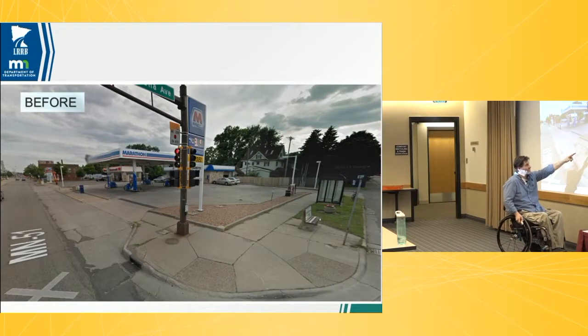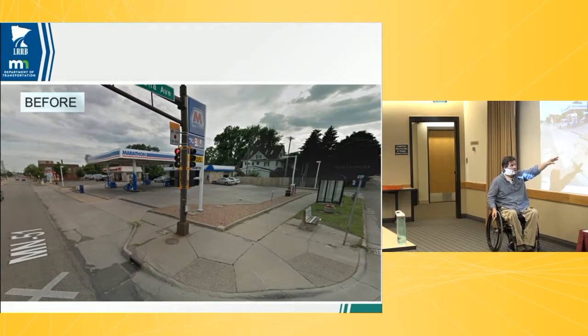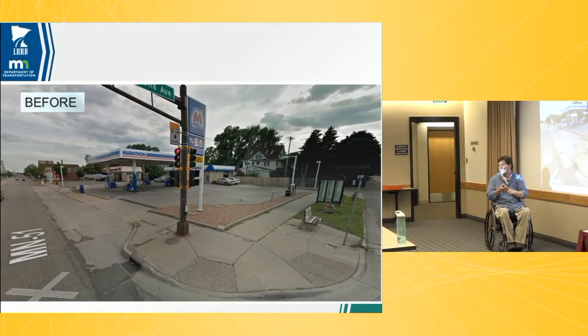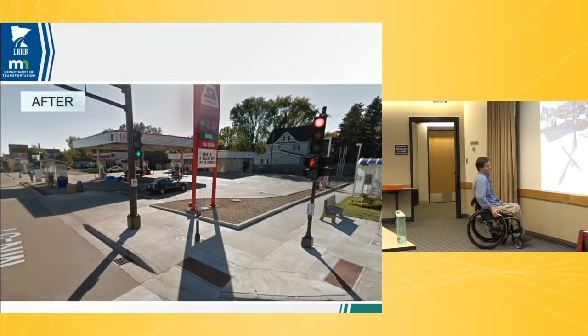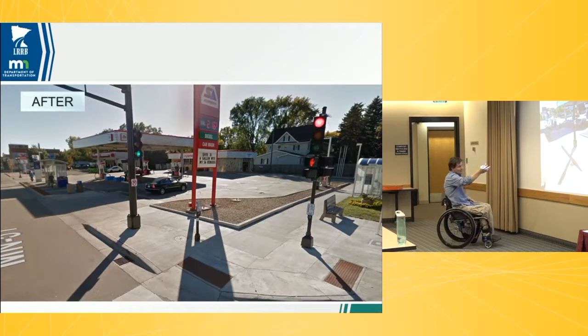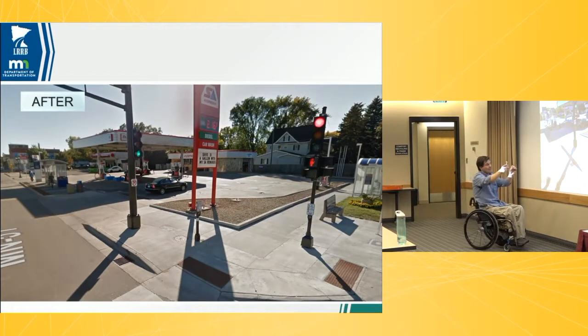Again, there's less than a 4-foot PAR between that light pole and the V curb. We can't get right-of-way, so it's got to stay there. So what are you going to do? Move the pole. 15 grand, move it out of the way. See what happens? There you go. Maintenance access route, no problem. Directional PARs, directional curb, APS all works. Didn't get into right-of-way.